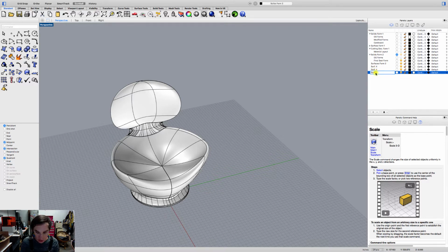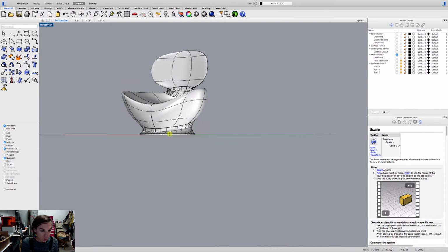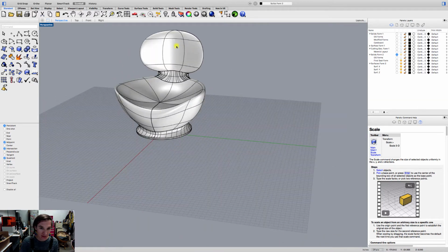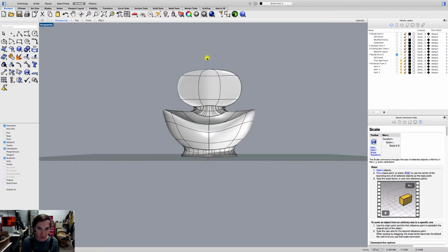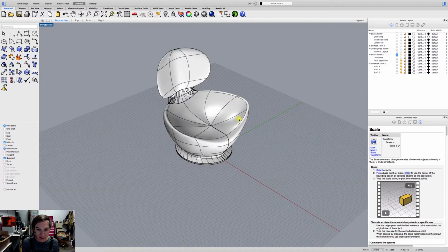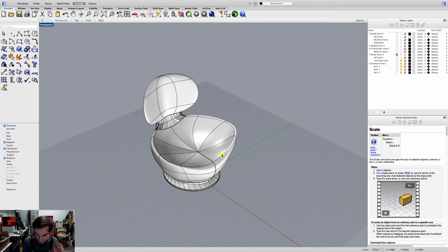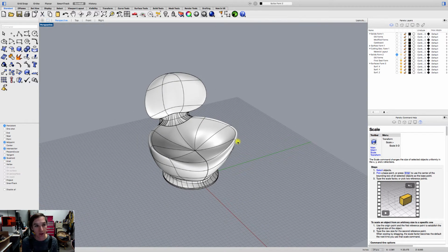And what's going to help me generate these is a command called contour. All right. So why don't we work in the Y direction right now? I'm going to generate the surfaces or the lines, the cross sections of this going in the Y direction. So it's going to slice sort of as if we're looking onto it right now. And I say that that's the Y direction because I'm going to point my contour line into the Y direction.